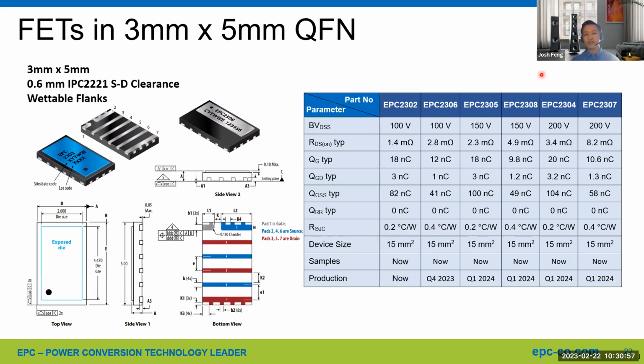So if for any reason you desire a lower voltage device, and for any reason you need to swap to a higher voltage, you can basically just desolder the device and put in a new higher voltage device. If you have some current sensing, you might have to adjust the current sensing limit. But otherwise, in terms of footprint compatibility, this is something we're trying to target and hopefully benefit our customers with very scalable platforms for QFN implementations.